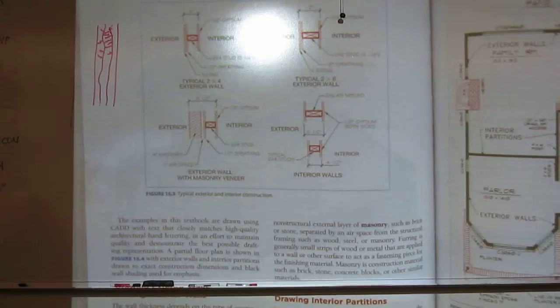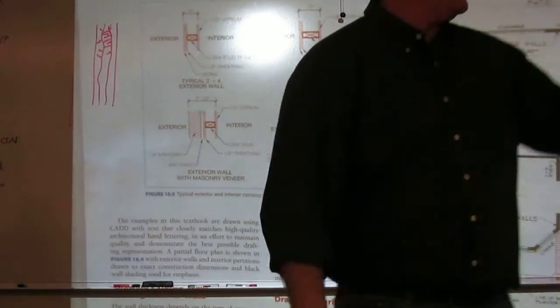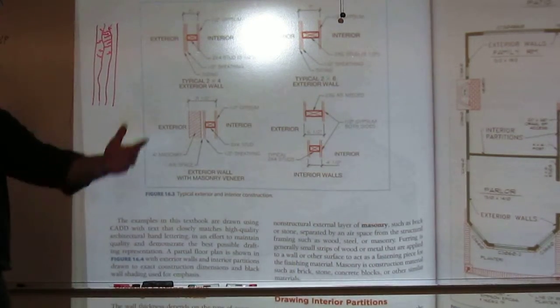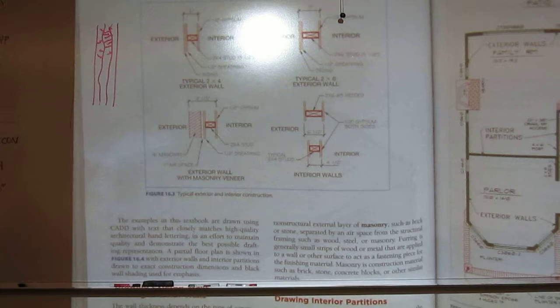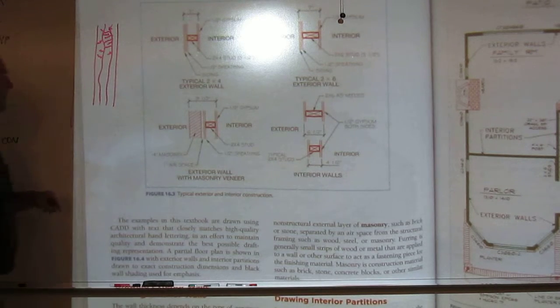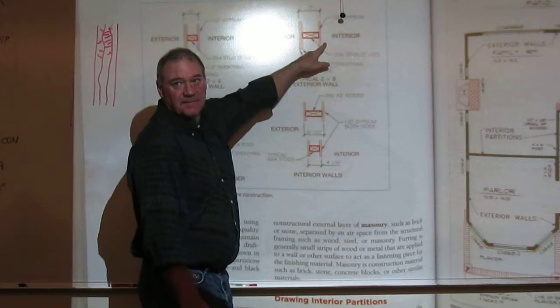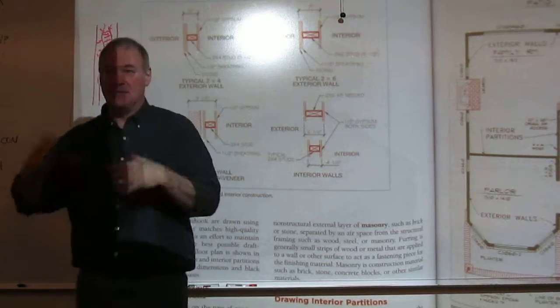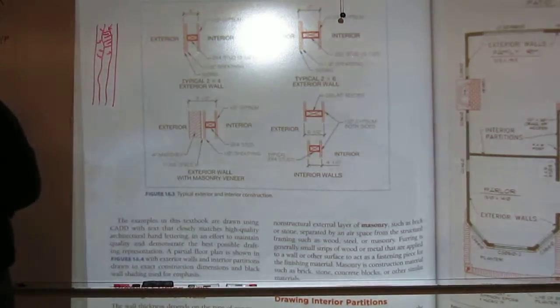Now, these have been sitting here for a long time. In fact, I brought those in probably 15 years ago. So they might have shrunk a little bit more as moisture has gone out of them. They might be a hair less. Okay, so bottom line, exterior walls: show the stud, 5.5 inches, and the 1/2 inch sheetrock. That's why I said draw these exterior walls at 6 inches.